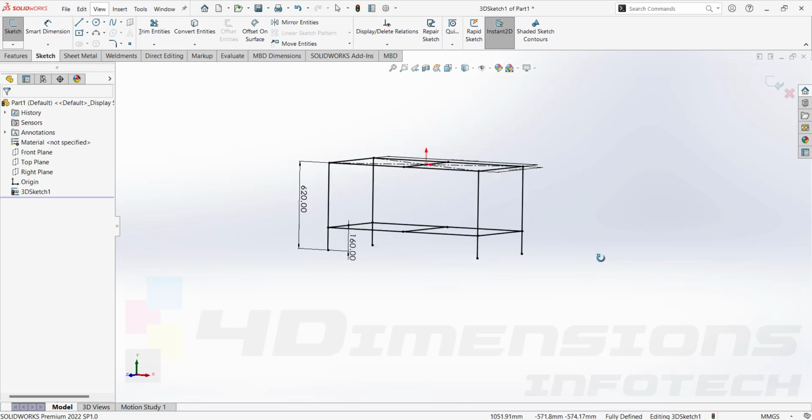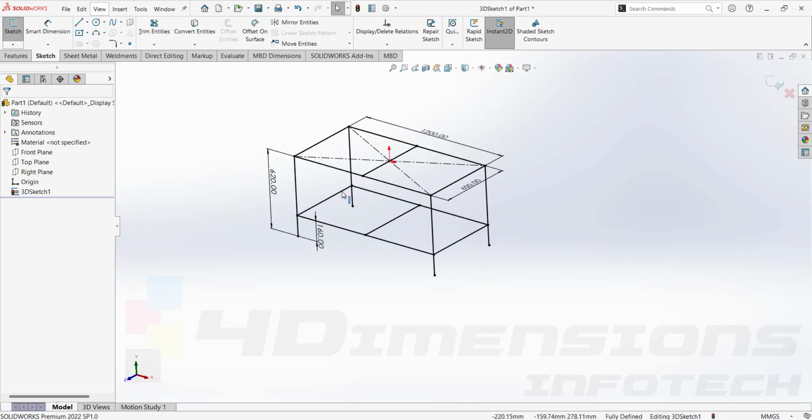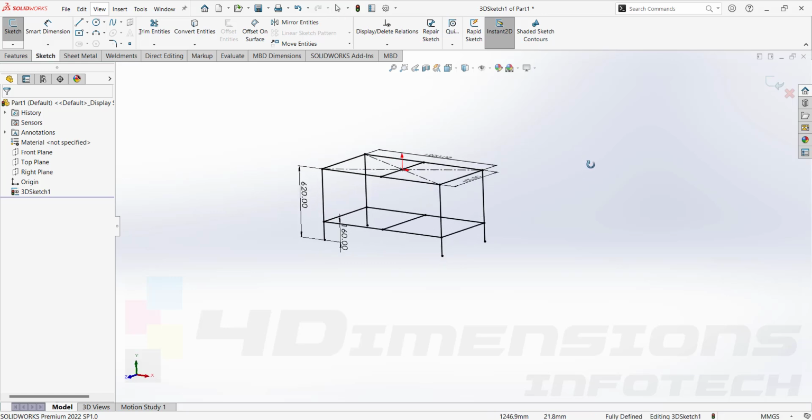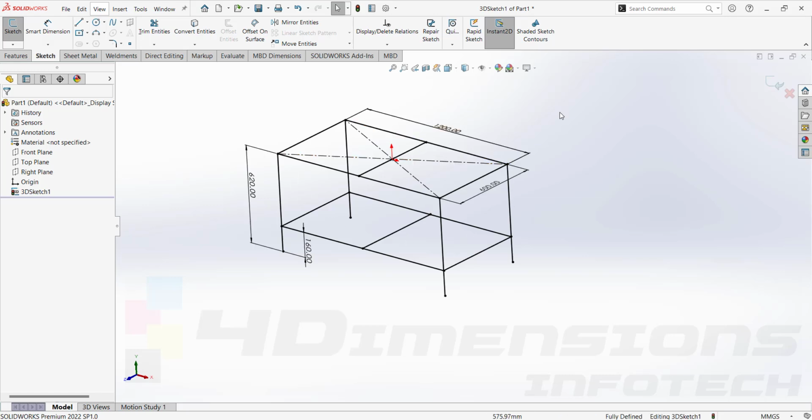Why is 3D sketch referred to mostly? It is because if you use 3D sketch, you don't need to make multiple planes here to complete this sketch. But in 2D sketch, you need multiple planes so as to complete this kind of complicated sketch there. So to avoid planes and to work in a single sketch, it is better to go with 3D sketch. Or else you can use 2D sketch also, as we have used in part modeling earlier.